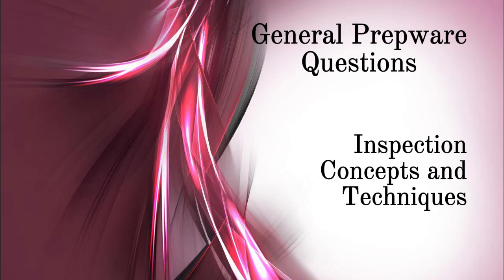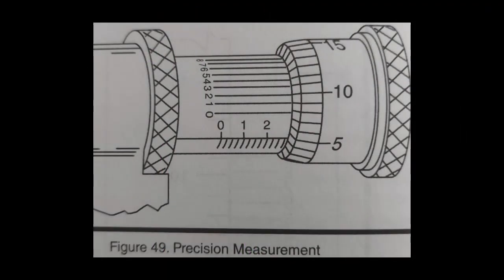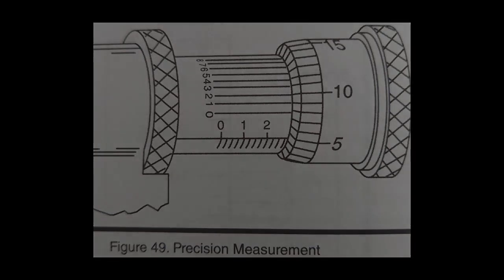The twist of a connecting rod is checked by installing push-fit arbors in both ends, supported by parallel steel bars on a surface plate. Measurements are taken between the arbor and the parallel bar with a thickness gauge. Which tool can be used to determine piston pin out of round wear? Micrometer caliper. Refer to Figure 49. The measurement reading on the micrometer is 0.2792.